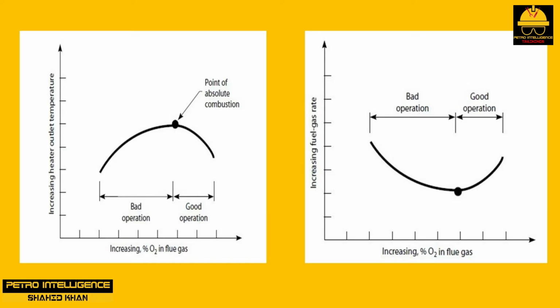Are we trying to make the flue gas to some particular oxygen content specification, or are we trying to save fuel? Certainly, the answer is that we want to get the most heat we can out of every pound of fuel. Well, then, dear viewer, let us neither set nor encourage the use of these stack or flue gas oxygen targets. They are meaningless and often cause more harm than good.